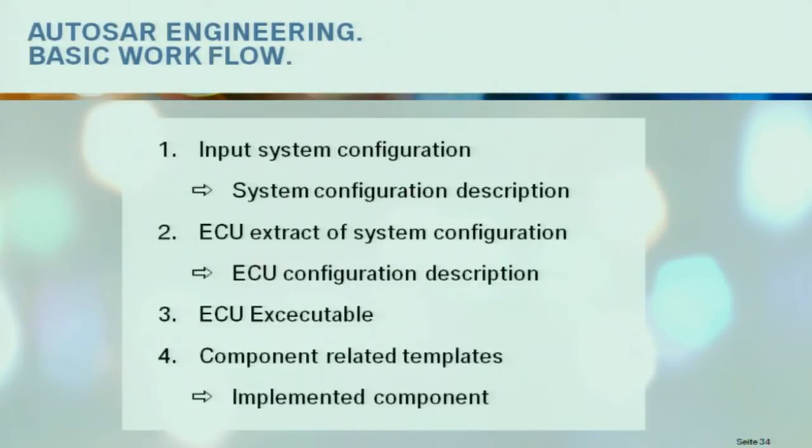Later on, you can generate, by mapping the software components to the ECU, the executable, and you get a component-related template for each software component, which means you get the function calls to the RTE. This is generated automatically to establish the communication. And this is the basic top-down workflow for AUTOSAR.